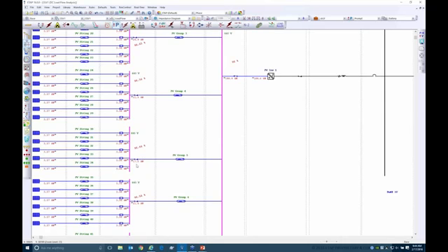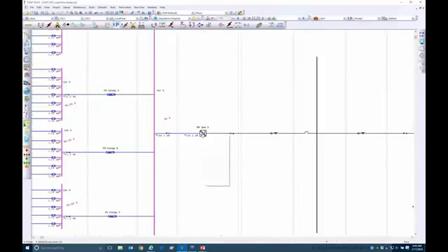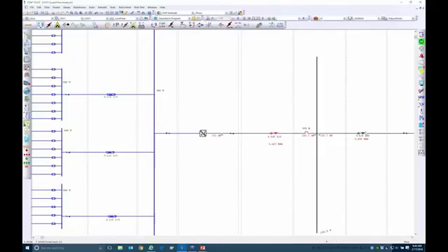But because the number of strings are different, you'll see 21, 17, 21, and so on. You can see the voltages at each combiner, the flow through each of the combiners, and the input into the inverter. And then we stop right here because this is the extent of the DC power flow. You can save this operating value into the inverter and then follow up with the AC calculation. So you can now see the AC injection into the grid.